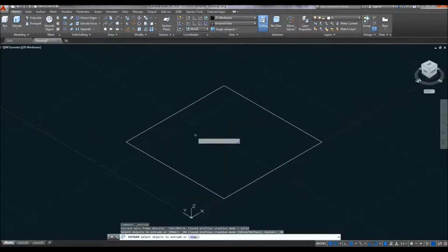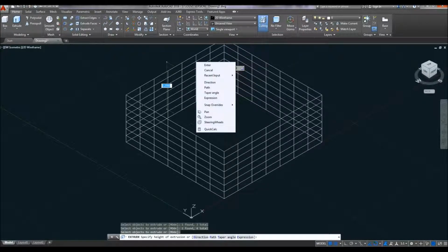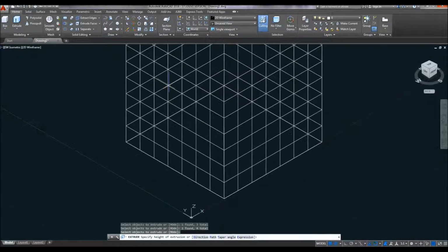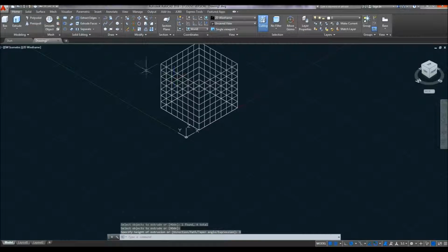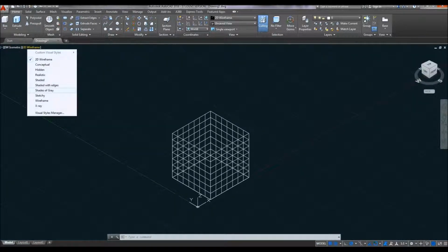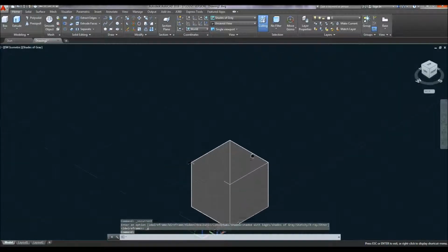I realize that in this edition, you have to select the tool and then select the lines. So I do that, not realizing that I wasn't set up the right way. I had 2D wireframe on instead of shades of gray, which I'll show you how to change in a second. So right now I'm typing in 3x3 cube, and then I realize it's not going to work. So I go here, I hit wireframe, you can see it highlighted in yellow, and I go down to shades of gray, and I figured out that still didn't work with extrude.